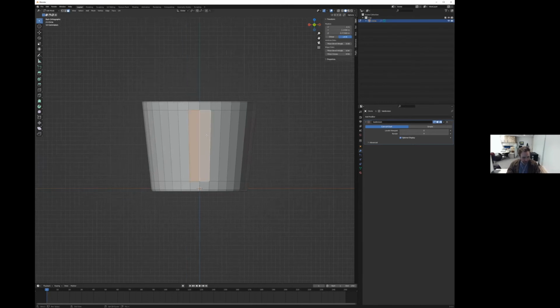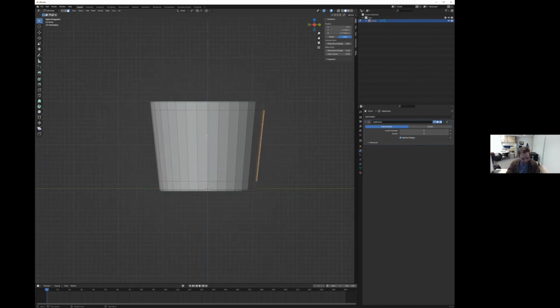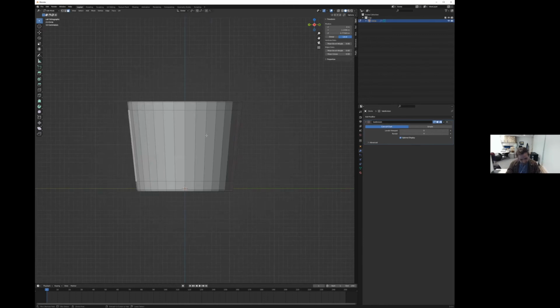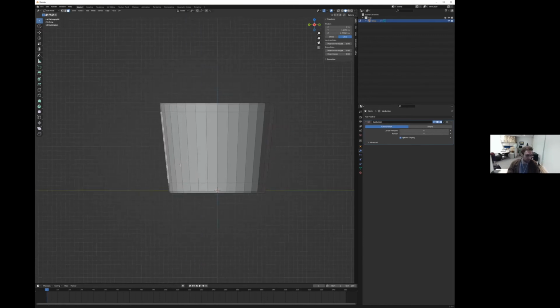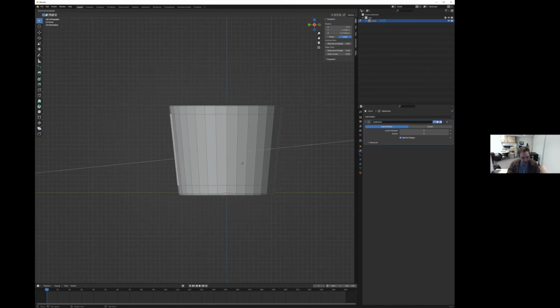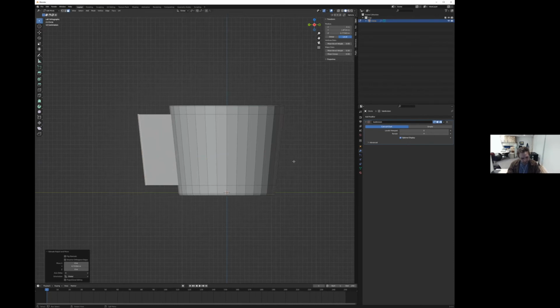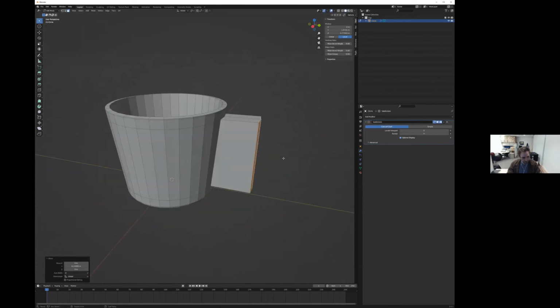For me, I'm looking directly at the Y. So I take 2 of these faces. I press 3 so I get a side view. If I press Control 3, I look at the other side. And then I'm going to press E to extrude. I'm going to extrude this on the Y-axis since that's the direction of where it's being pulled. Okay. I can press R to rotate, maybe straighten it a little bit, and then G and then Y to push it out a little bit. So now I have something that looks like this.